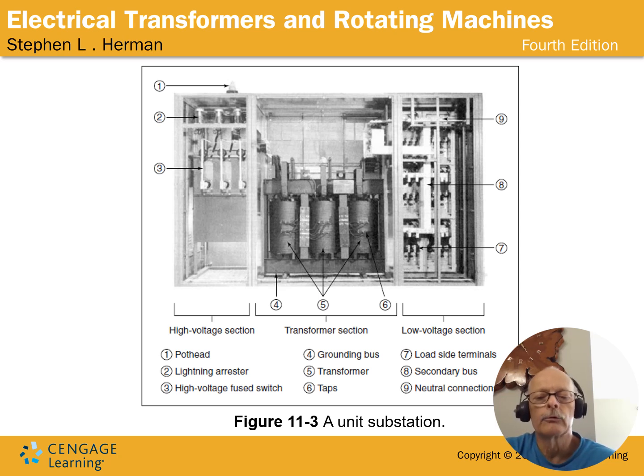In between, it is converted, say, in a case like this, from 7,200 volts down to 480. Or maybe it's 480 down to 200 so that you can run a bank of machines. You can't tell, but you can see that there's limited airspace in here, and with limited airspace, you're more likely to heat up. That's why it's important to make sure the ventilation is clear. There are ventilation holes in the bottom, in the back, and the top, so there's room for air to flow, but it's up to us to keep it clean.